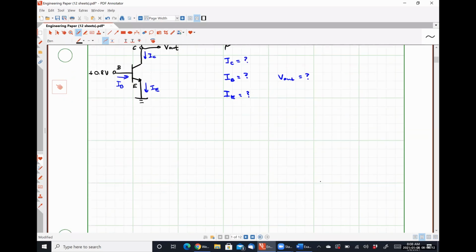So our large signal model representation of this circuit. Here's my base. I'm assuming that it's operating in the forward active region. And we will need to prove that technically, because there is a possibility it could be acting in saturation mode, depending on what the value of V out is. So let me explain what I mean about that real quick. IB plus VBE.